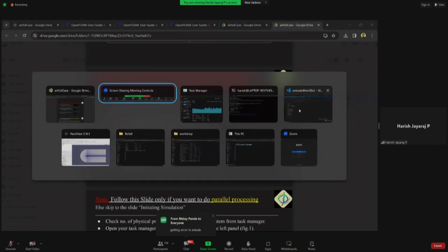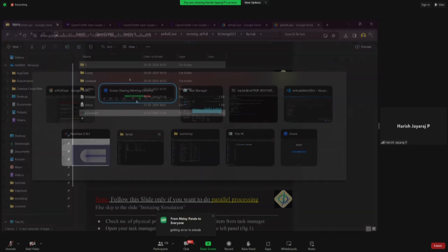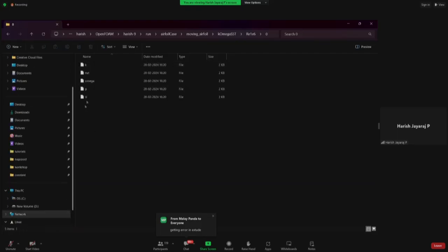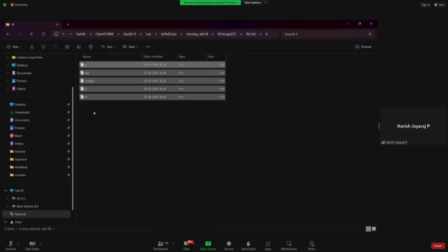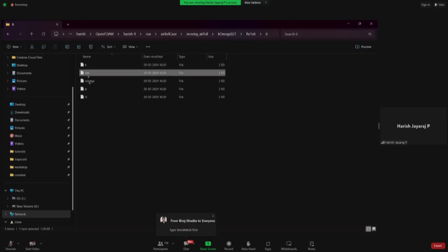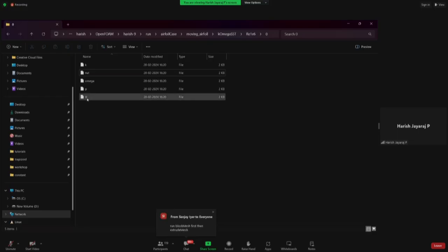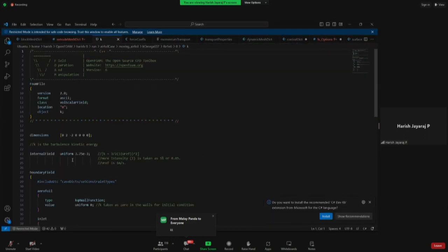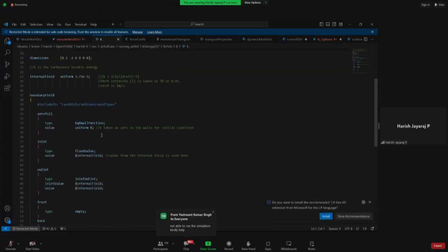So we are going to define these in the boundary files. If you remember, 0 is for the boundary files. When you go inside the 0 folder, you will find all these 5 files: U, which is velocity, the pressure p, k, omega, and nut. Based on what you have done previously for the icoFoam and simpleFoam cases, you will have an idea of what the pressure and velocity files are. But for k, which is a part of the turbulence model k omega SST, once you open this file, you will find something like this.